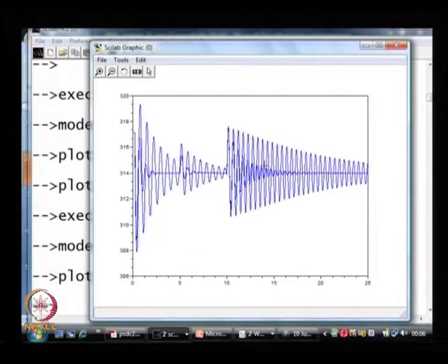well, you notice something. In the original program, the damping was much higher, whereas now in all the transients which are considered, one thing you can notice is that the transient takes a longer time to die down. In fact, in a synchronous machine with one damper winding less, it appears that the damping has reduced.